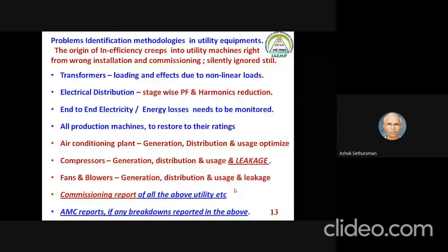If the compressor house is cool at the ambient temperature, say it's around 40 degrees, the house should also be at 40 degrees. If the house is at 45 or 50 degrees, this shows you are losing almost 5 to 10% of compressed air within the compressor house itself.